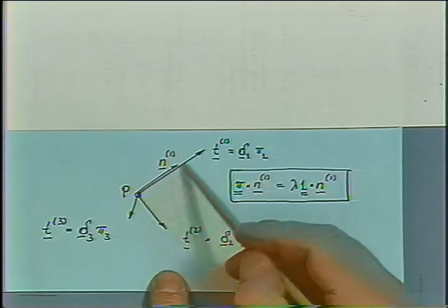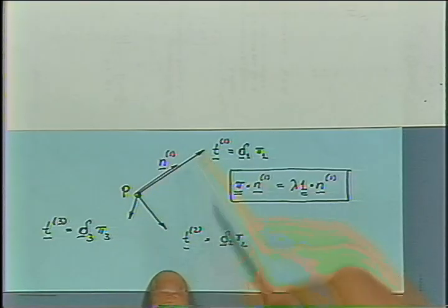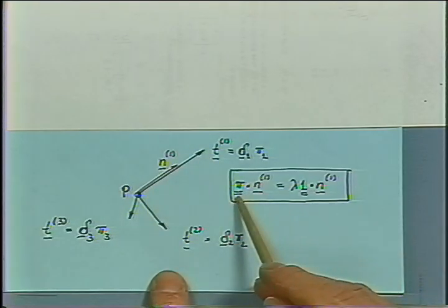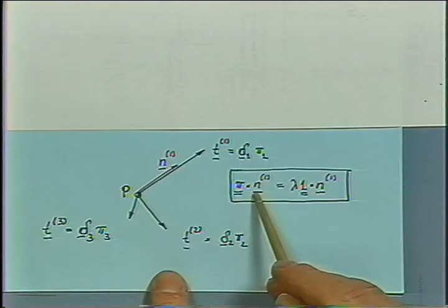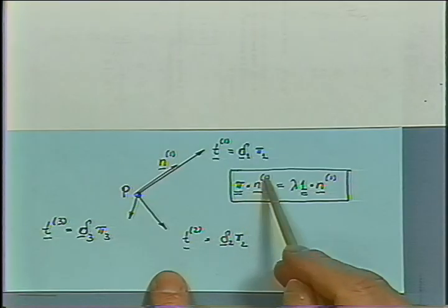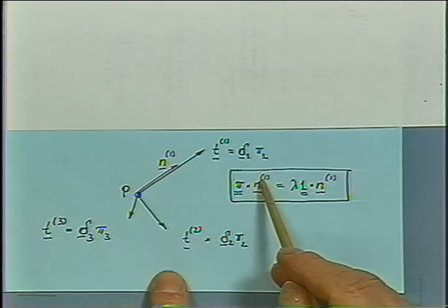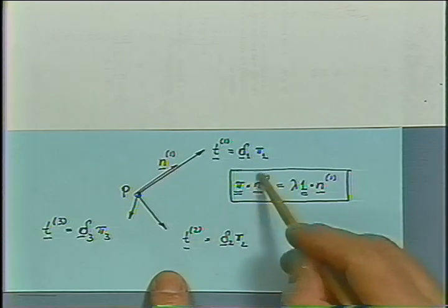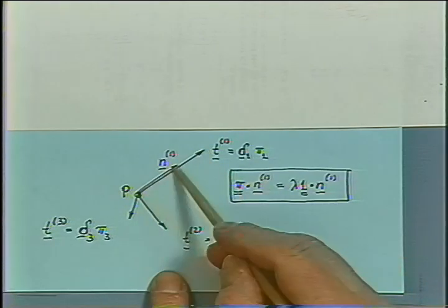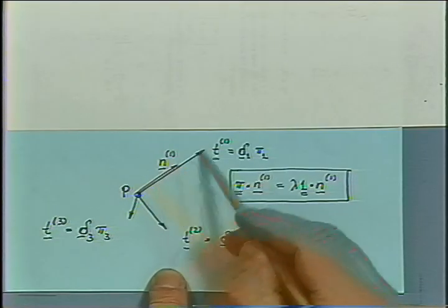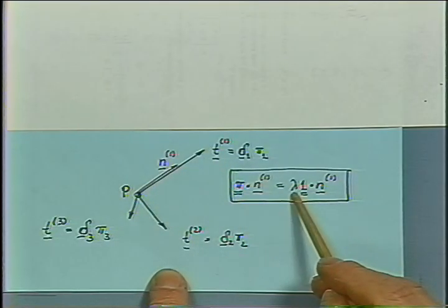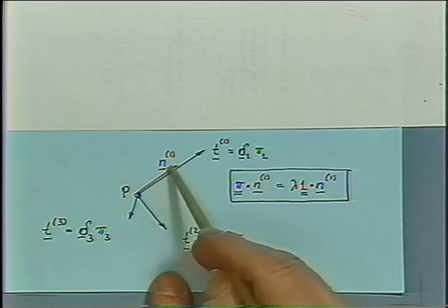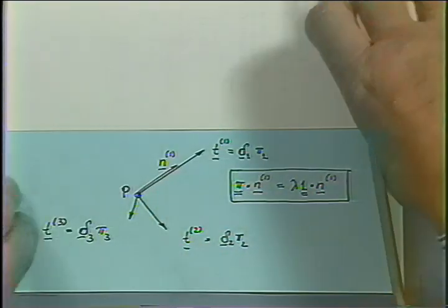n is collinear with the principal stress in one direction. And we can write this down now. We could say the traction in this first direction would be n times P, or P times n, doesn't matter. And n would be the first normal vector, a principal unit normal. And this traction vector is just equal to n times some factor which stretches n. And this factor is lambda. Okay? So n and the traction are collinear, and n is just stretched to produce the first stress.